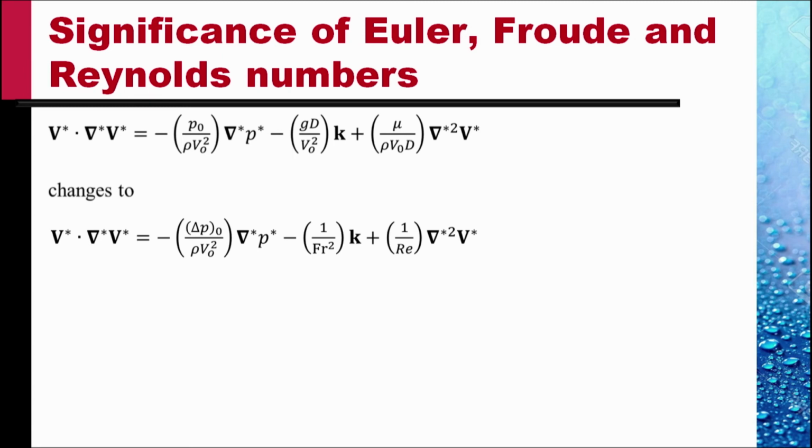If we make the changes, the equation that we started with changes into this second equation. And the pressure boundary condition becomes Pg star tends to 0. The gauge pressure non-dimensionalized tends to 0. So if we do this, then pressure P naught does not occur anywhere in this equation. Instead, a delta P naught has been introduced.